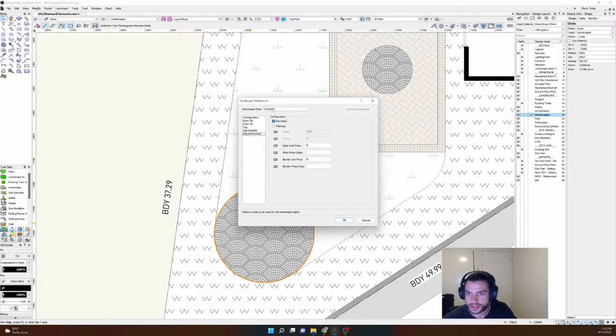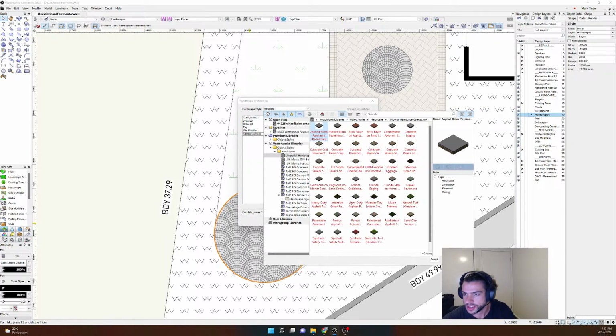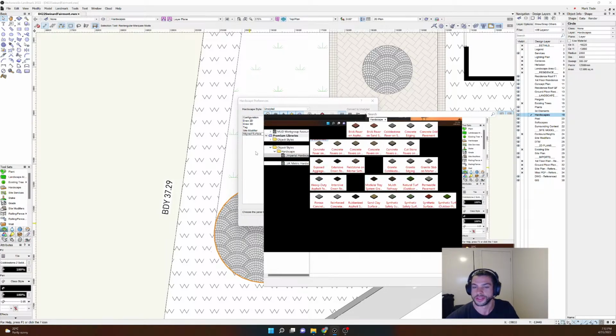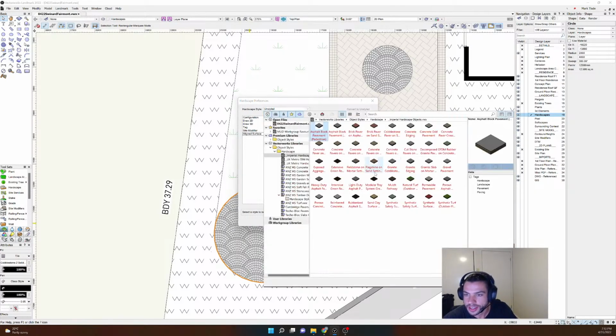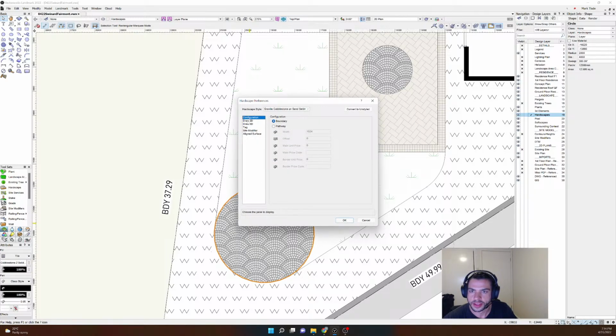And I've run into a common problem with this. Whenever I rechange this, oh no, it's not doing it now. Sometimes whenever I rechange it, this only happens when I'm streaming. I'm really not sure why, but whenever I reshape it, it does that. So we got flagstones instead of granite cobblestones, which I was just going to use with this hardscape style. It'll try and import new hatches for certain components. If they're already in your file, you can just say do not import the hatch, use the existing hatch, unless of course you want to change the hatch that's in there.